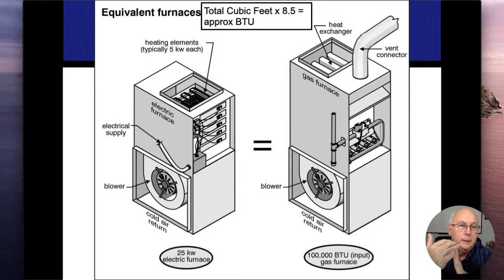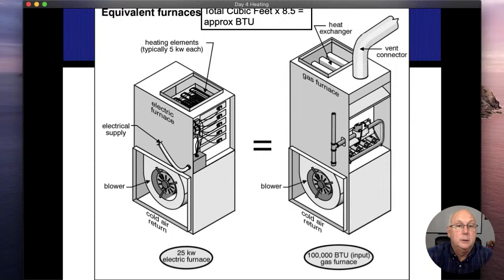With the electric furnaces, we're actually going to put the air conditioners before the electric furnaces. I take that back. First it's the filter, then the air conditioner, then the blower fan, and then the heating coils. These are thicker and they're just not worried about being damaged from the air conditioning unit.